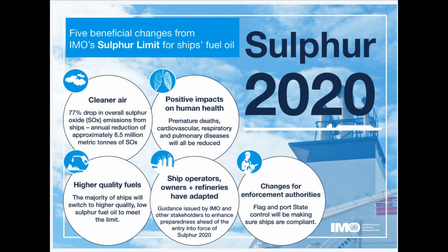Exhaust gas scrubber technology. The exhaust gas from the engine is passed through the scrubber tower where water is showered over it. There are two types of systems. One, closed loop system, where fresh water blended with caustic soda is used as a scrubbing liquid which reduces the SOx by 95%. The scrubbing water is then sent to a water treatment effluent emulsion breaking plant, after which it can be discharged overboard.